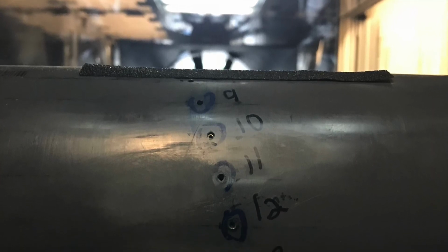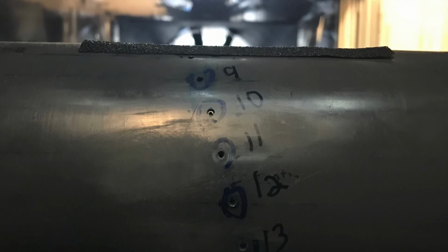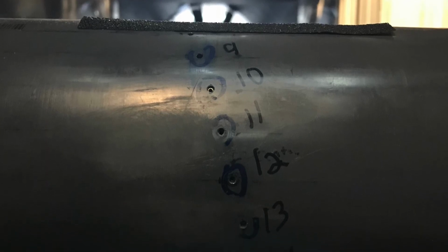For the experiment, we tested pressures for the untripped and tripped cylinders. For the untripped cylinder, the flow separated around 75 degrees from the front of the cylinder at all RPMs. We placed the trip strip 15 degrees to the front of the top and bottom of the cylinder, which turned out to be right where the flow separated according to our data.